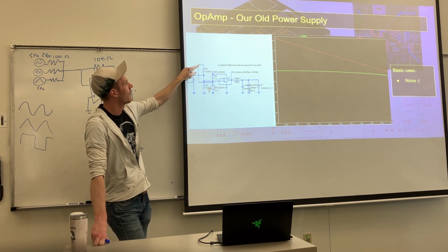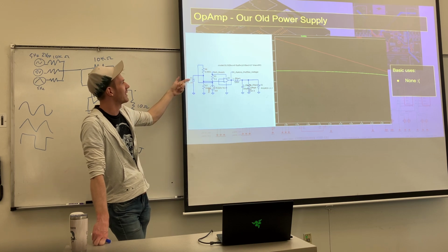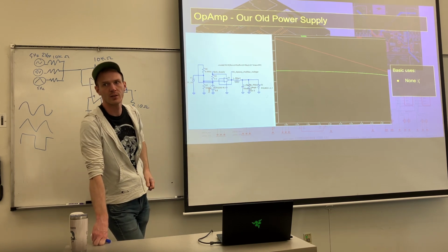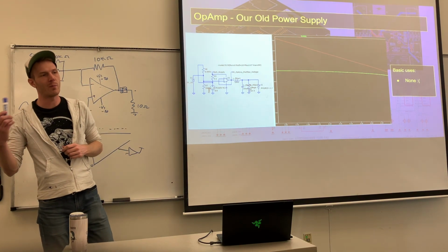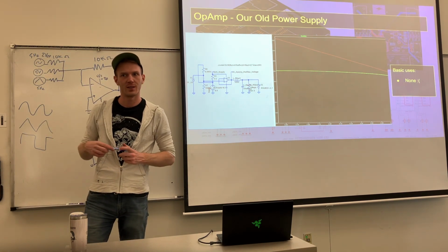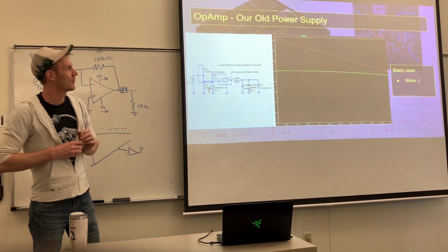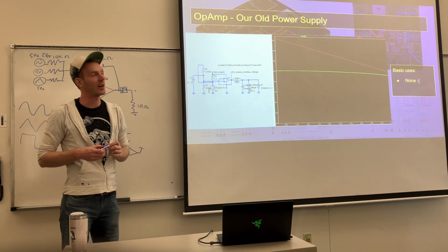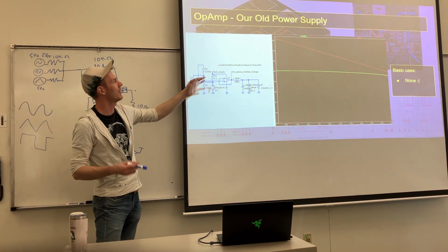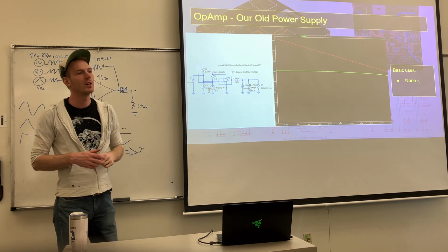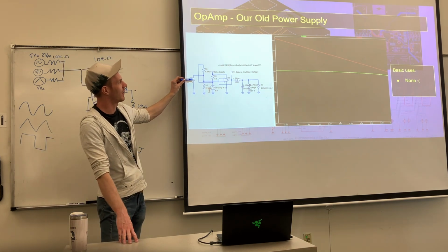Now what's the purpose of this resistor? If this is already giving us 5 volts, why do we have another resistor here? Think back to what the main uses of a resistor are. Is it limiting current? Limiting current. So we don't want to send 500 amps through this thing. So we have a moderately sized resistor, not huge, not small, chained up to this Zener diode.